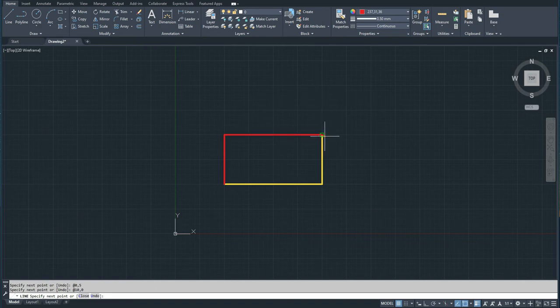Now, from here, guys, I will go to here. Again, shift 2, which is at, and then we will not travel in x direction, so 0, comma. We will go in the negative direction of y by 5. So minus 5 in y direction. So at 0, minus 5. I will go back to this point. From here, it will be shift 2. I will travel in negative x. So we have minus 10 because the line length is 10. And we will not go in y direction. So I will choose 0 in y. This is called relative coordinate system.